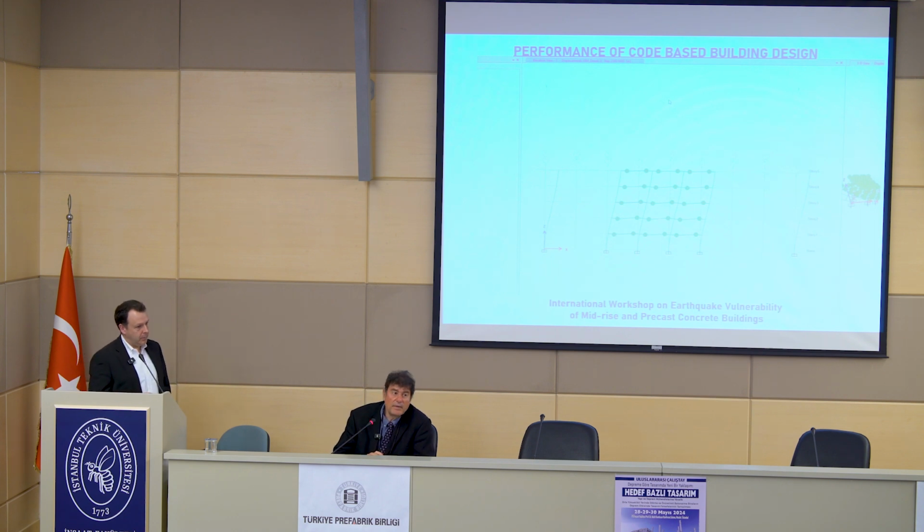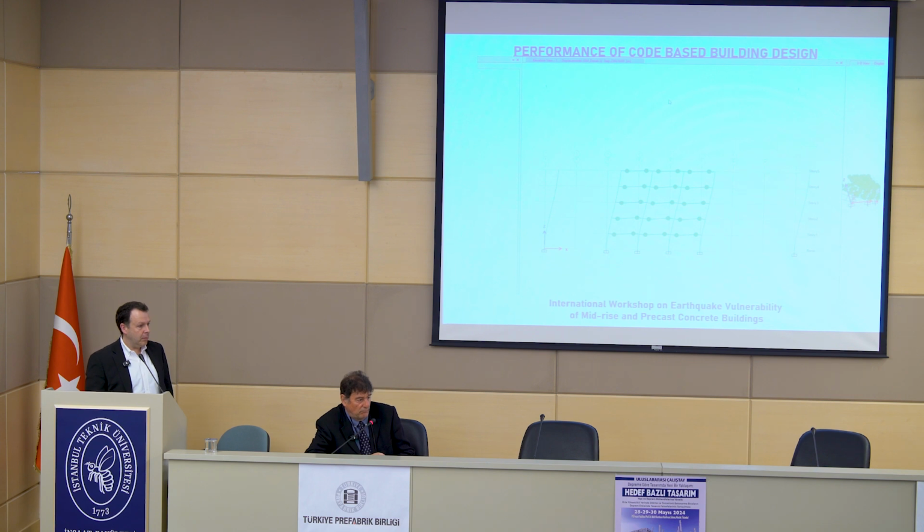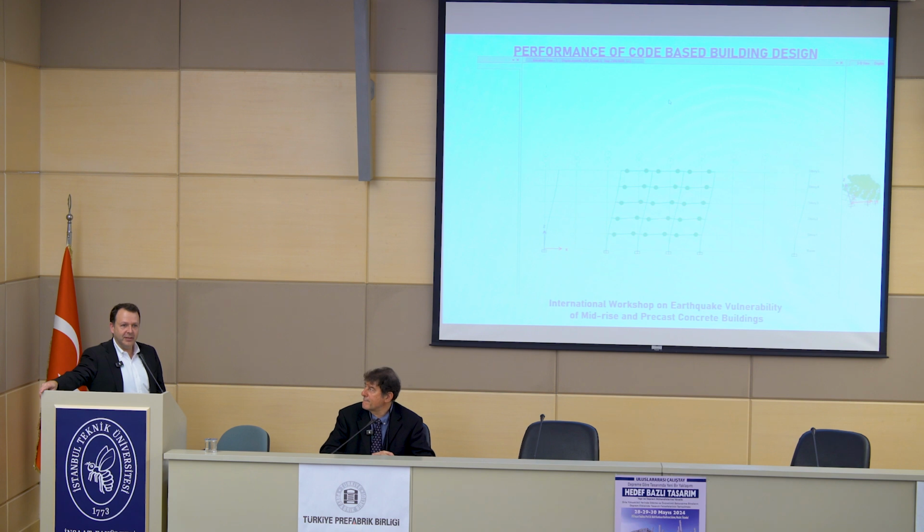Okay. This concept that you define as specific is not event specific. It's a sort of idealization of main earthquakes. What I noticed is that when you define it by spectral velocity, it's event specific. So do you always do that, or would you have to convert our acceleration spectra to a velocity spectrum by using angular frequency, and could you use that as an idealized setting? Did everybody understand the question?